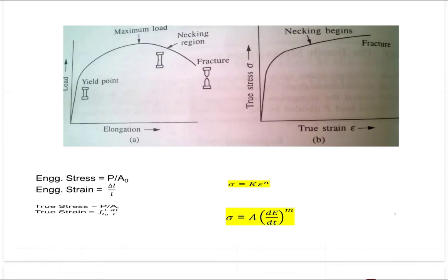In this curve, you are seeing first again the linear portion, which was the elastic. When the yield point comes, the material transforms from elastic to plastic. Now this is a non-linear curve. Here, this part we call the material is plastically deformed and it will be non-recoverable now.